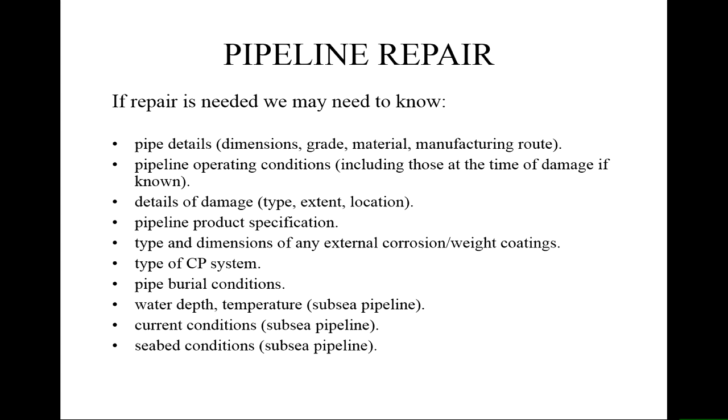If we decided that repairs are needed for our pipes, then we need to know, as you can see from these ideas on the slide, pretty much everything about that pipe. Details regarding dimensions, grade of the steel, how the pipe was manufactured.